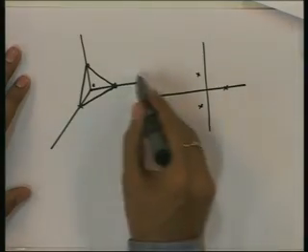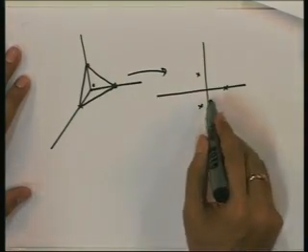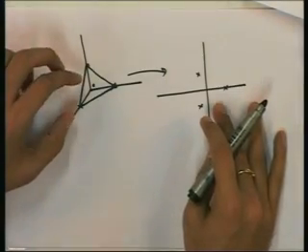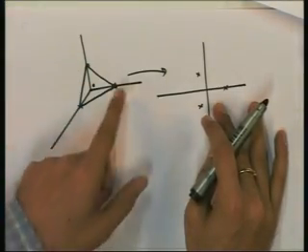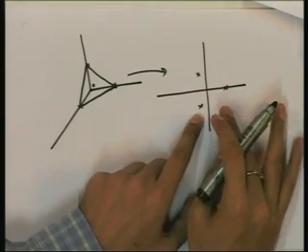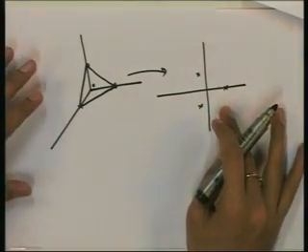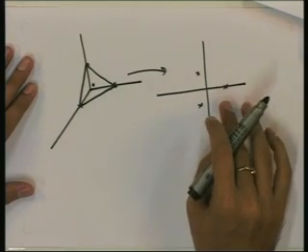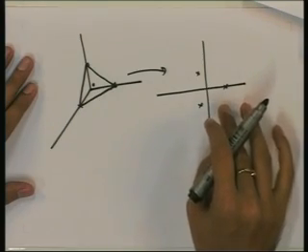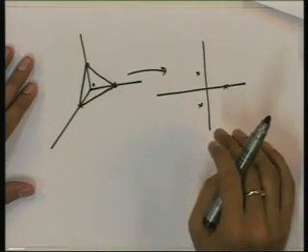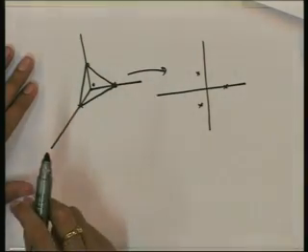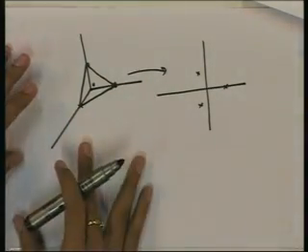So it is also equivalent to a 2-dimensional signal set. A 3-dimensional FSK orthogonal signal set is equivalent to a 2-dimensional signal set with 3 points. This kind of signal set is called the simplex signal set. Now, how do we know how much translation is required? That we will see.